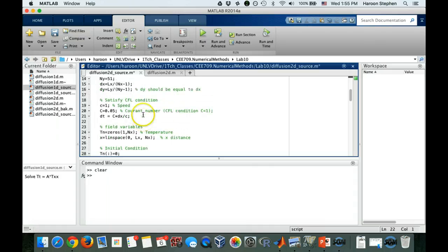And now the temperature will have two dimensions. In MATLAB, what seems to be the x dimension is actually the y dimension, because the x dimension is along this way, but these are columns. So columns are the second argument. So we'll put Ny here. This gives us the temperature matrix. And similarly, we can also create our y-axis information here, how our y-axis values change. These will be Ly, Ny, and then this is our y-axis distance. And using these two, we can create our mesh